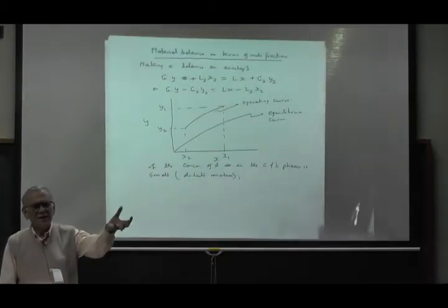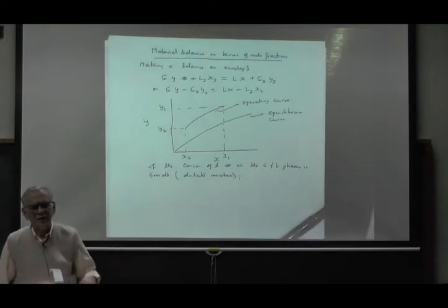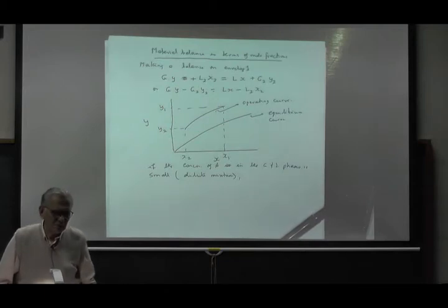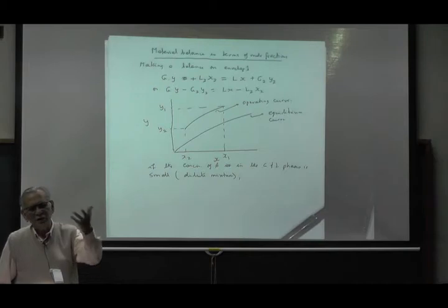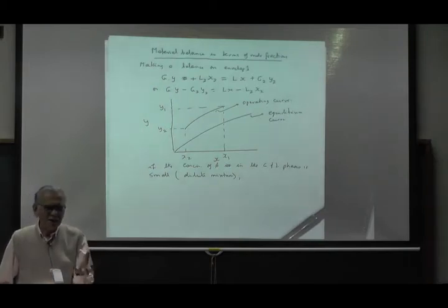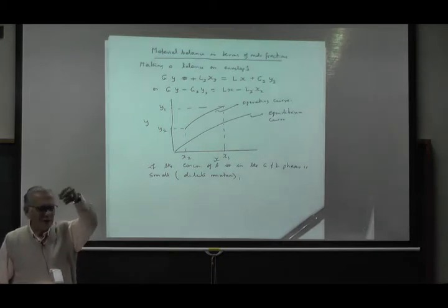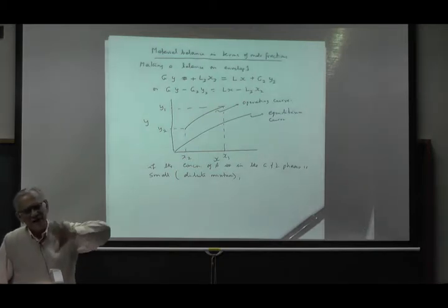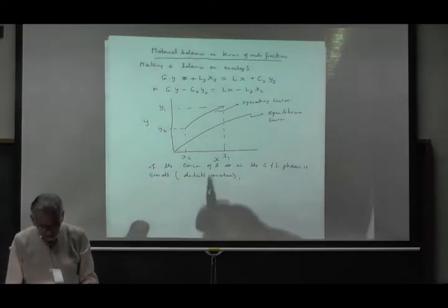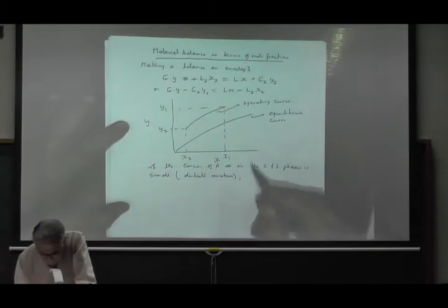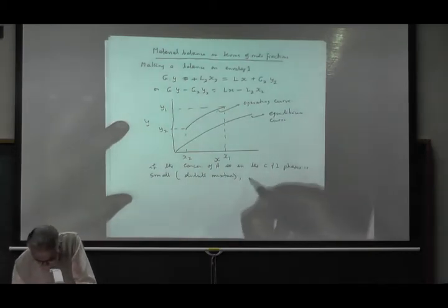See, let's again take the example of ammonia and air. Supposing you had 99% air and 1% ammonia, and you are removing 90% of it. So your flow rate is going from what to what? You had 100 coming in, and you are going out 99 point something. So your flow rate is nearly constant, even the total flow rate. So if your concentrations are small, then basically the operating line is approximately linear.